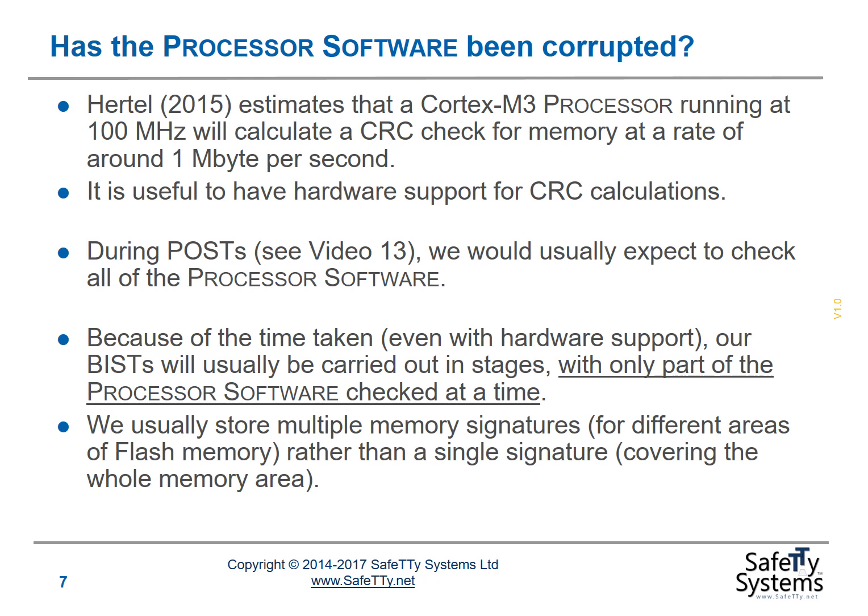As modern designs may be slightly more powerful than this, but they may also have more memory, it can take a significant amount of time to calculate the CRC. So in many cases, if you're going to use a golden signature or use CRCs in your system for other purposes, it's useful to have hardware support for CRC calculations.